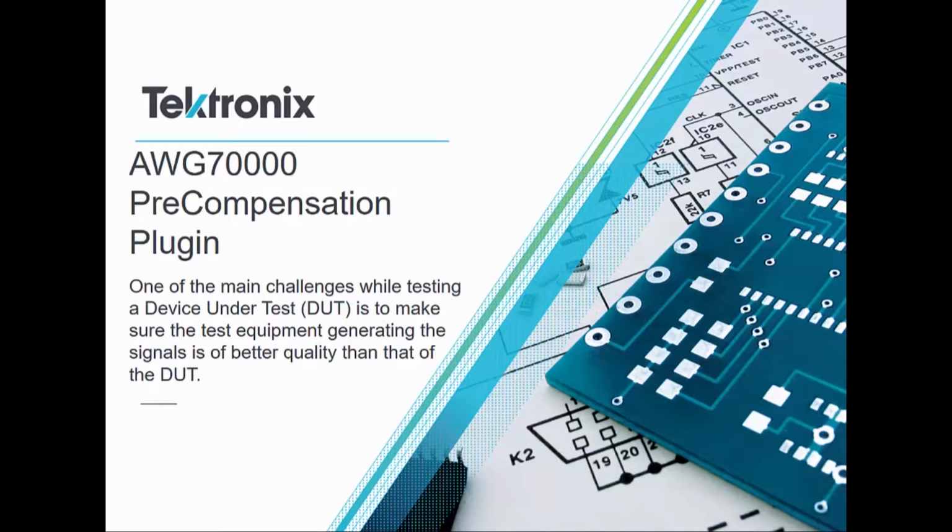Wideband signals created from signal generators are often limited by the bandwidth of the instrument's frequency roll-off and the losses associated with the cables, connectors, and external devices. This means that the influence of the generator's hardware and the connecting components create losses on the signals that can distort the signals and impact the ability to test the device under test appropriately. So these system artifacts need to be de-embedded from the signals before sending them to the device under test.